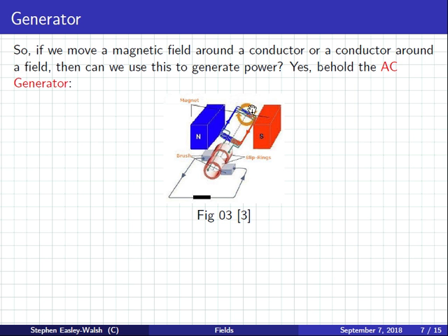And here you turn this wheel, so this guy turns around. Now, this side is connected to a ring, and this side is connected to a ring. They're connected loosely. What I mean is, you have your ring, and they touch like this, so when it turns, it just brushes against the ring. Now you might say, well, why don't you just connect it directly? Well, you can't, because if it turns, then the wire will twist up. And that's the end of it.